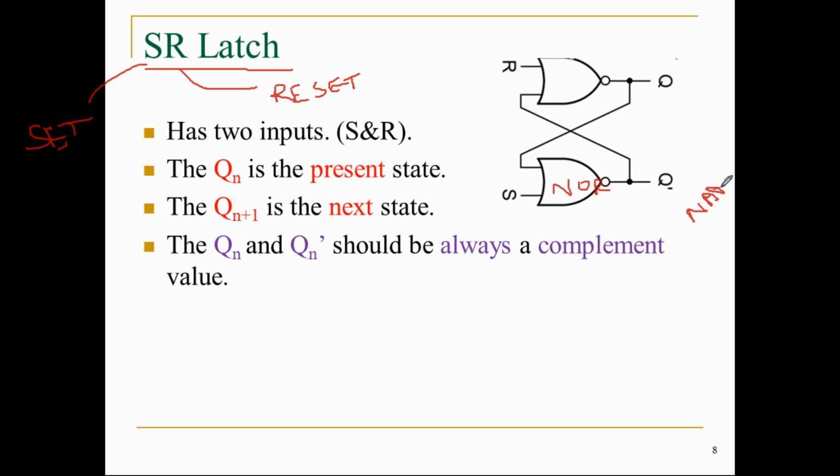You know about these two logic gates. These two logic gates are also called universal gates. What is meant by universal gate? It is a derived gate. By using this, we can get all the fundamental gate operations along with derived gate operations. Universal gates are gates by using which we can implement all other logic gate operations.